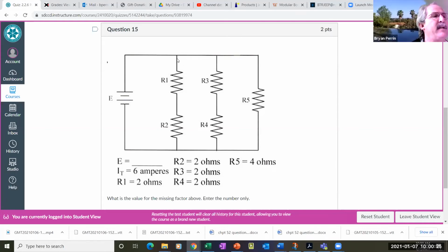Right. So what I did is I got 4 ohms on this leg, 4 ohms on this leg, and 4 ohms on this leg. So the formula says take 1 of resistor 1, so this is the first, 1 of resistor 2, which is my second leg, and 1 of resistor 3. Well, 1 divided by 4 is 0.25, right?